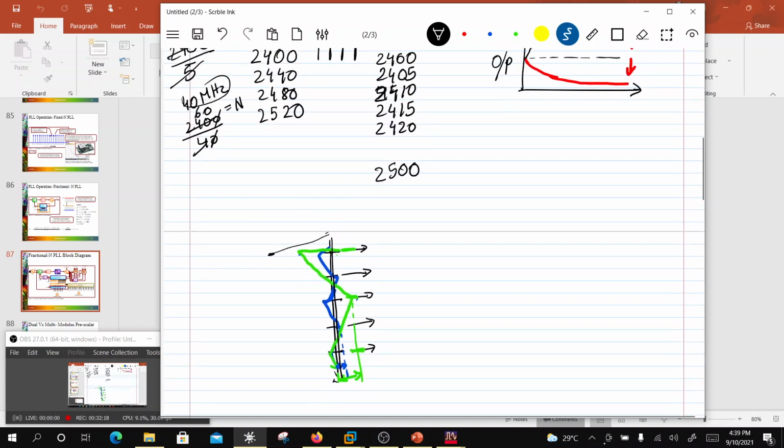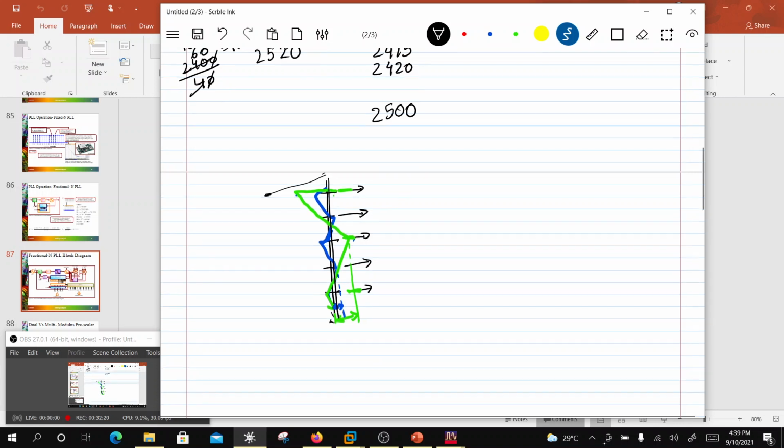So this is an example to show that if there is a DT approximation of a CT system, then there is a certain sampling rate for a given frequency at which you have to make the correction so that it remains within a certain tolerance. Otherwise it's going to become unstable.